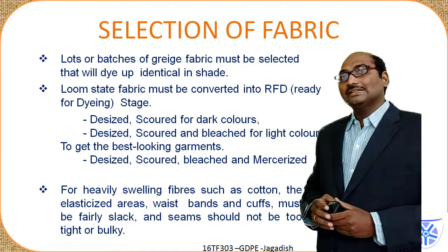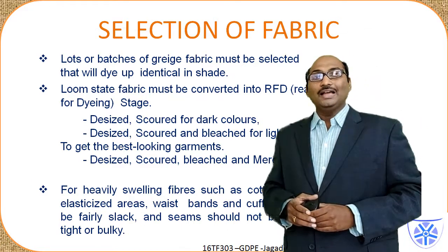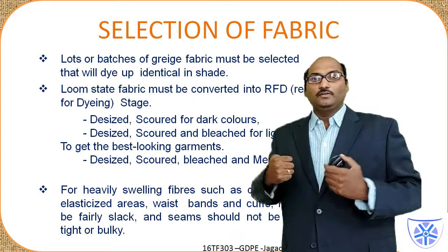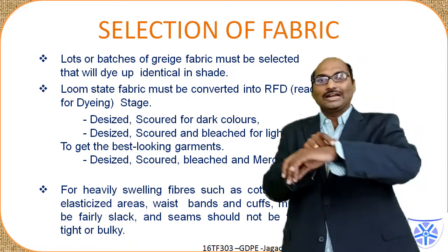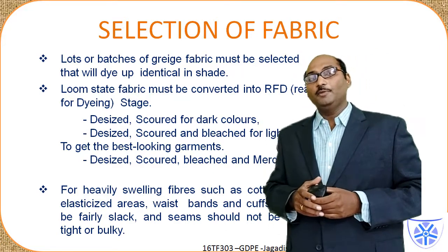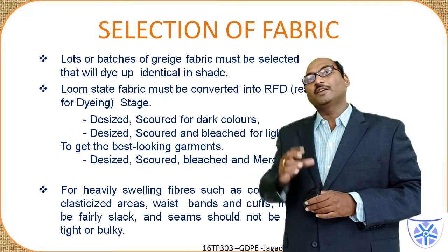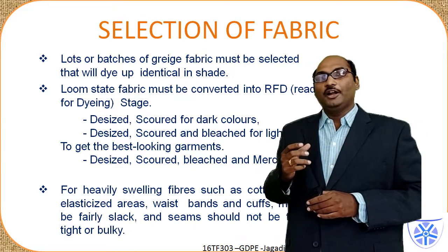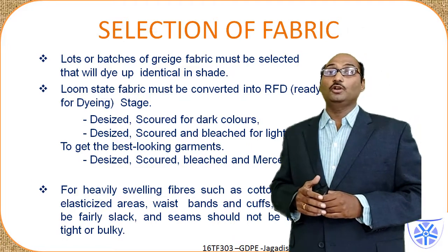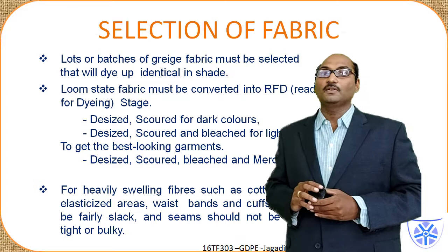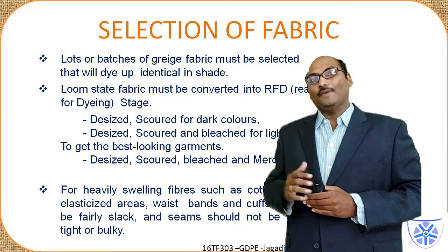For heavy swelling fibers such as cotton, the elasticized areas like waistbands and cuffs must be fairly slack, meaning loose, because sometimes shrinkage will happen and it will become tight after garment dyeing. So before the processing itself, those places should be loose fabric.